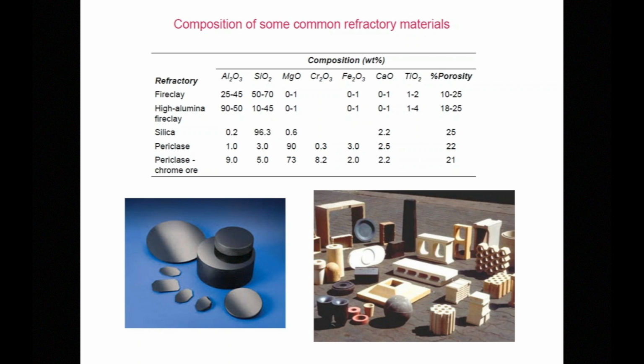Now, that degree of porosity is actually quite important because the ability to transfer heat or to allow heat to be absorbed through the ceramic materials means that temperature will have a very high conductivity with basically either air or vacuum. So that degree of porosity is quite important for the selection of different refractory materials.